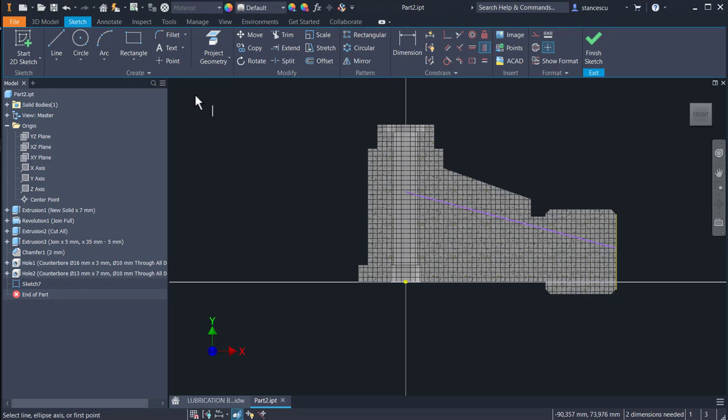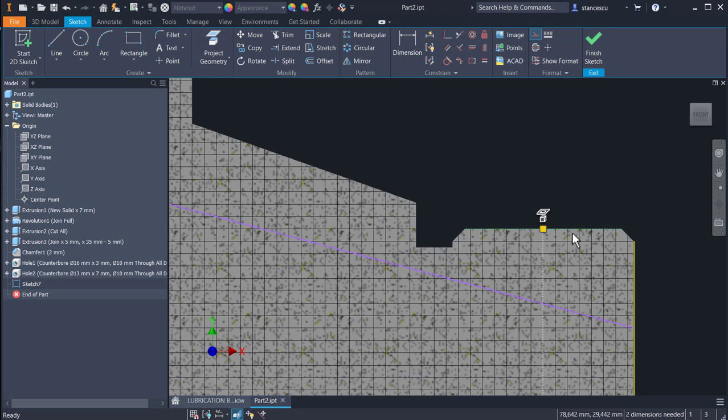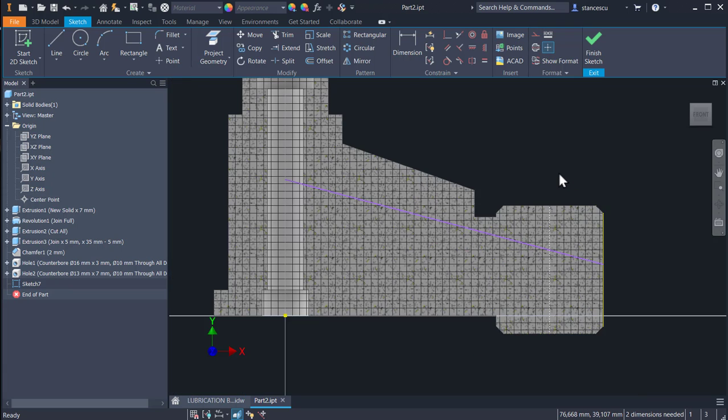So I create another line, which is construction line, between the midpoint and the midpoint. Yes, you must remark that these two are now construction lines. Not important, but you have to mind that if you select this as a general setting, you must expect that every line is also construction line.